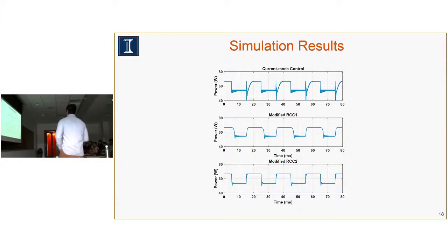And then these 2 do pretty well, though the one where you're flipping the sign of dp/dt seems to have a little more ripple in it, probably because the maximum power point becomes basically a triangle at that point. It's not a graceful curve as you see in normal IV curves.